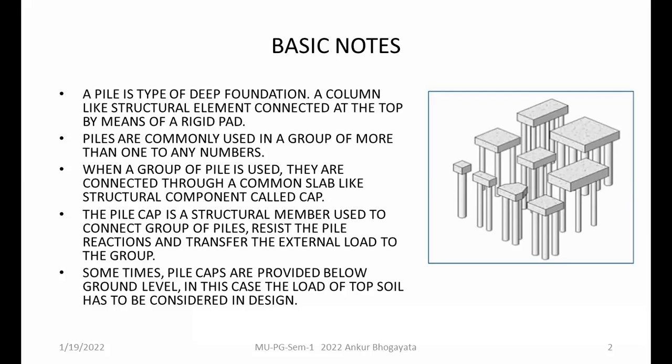So when the strong bottom is encountered, the pile is inserted and transfers the forces. So there will be a reaction, definitely, and because of this reaction, an upward force is applied to the cap itself. So you should understand that the cap is subjected to a dual set of forces. One is downward and second is upward.